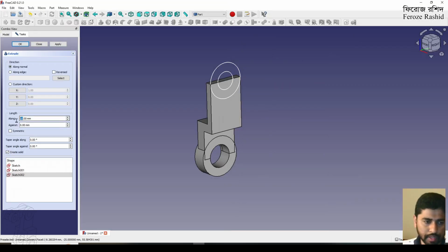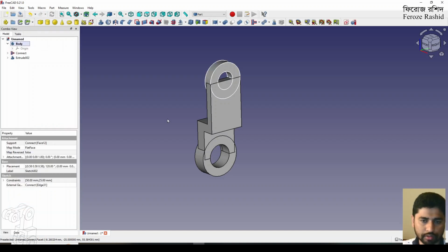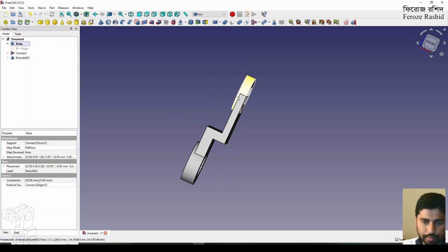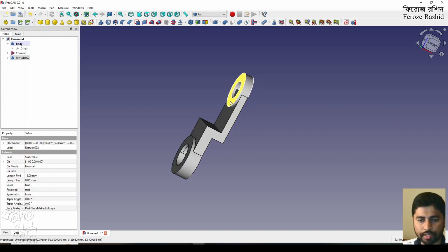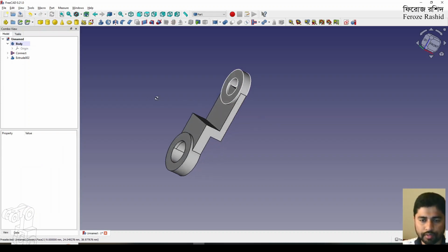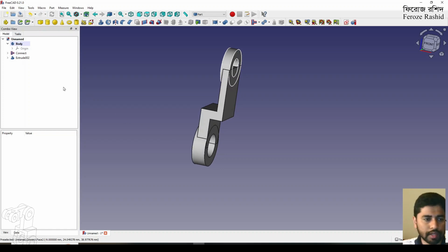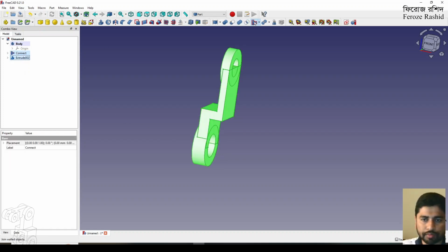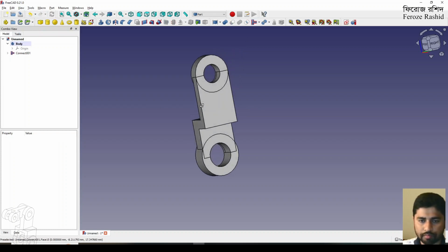So we will make it 9 plus 3 extension, and then we will make it reversed, apply close. So that's 3 millimeters extra here. It will be 3 millimeters extra on this side when we mirror it, and then we will come back to actually extend this face a bit more outside. Okay, we will use the same trick to connect between these two. Makes it easy.